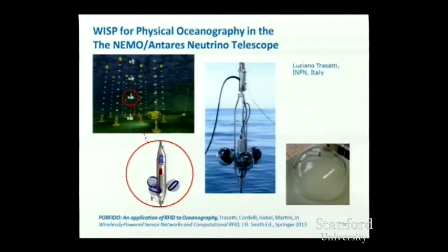they had this boundary, which is the glass sphere, that is not easy to breach. So they can't just add additional ports in this thing because that'll cause failures and it's expensive to create completely new housings like this. Plus each port that you have is further risk. So this is actually one of the examples of boundary integrity, where the key benefit of wireless power in this case is just getting through this 1 centimeter of glass, where there's a high pressure gradient across it, and so you don't want to have additional ports in that glass.